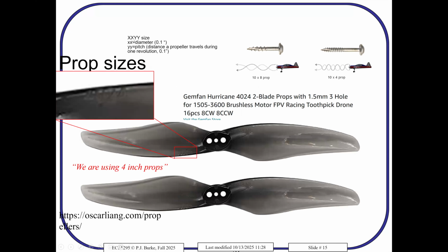So the prop size is specified as XXYY. XX is the diameter in units of 0.1 inch. YY is the pitch, which is the distance the propeller travels during 1 revolution in units of 0.1 inch. So it's like a screwdriver. You can have dense or sparse screws. So our prop is a 40-24. That means we're using 4-inch props, and 24 is the pitch. So that's the prop that we're using.